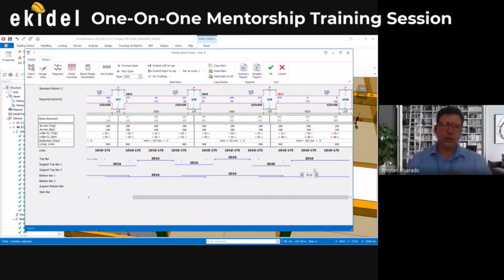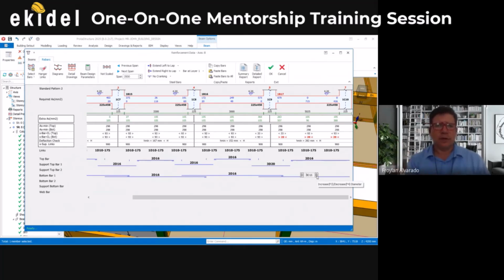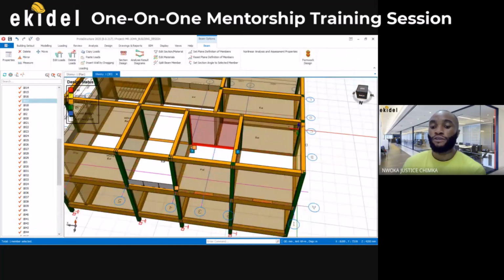But you would want all of them to be the same, no? Exactly. You have your cage reinforcement, and then you have your additional reinforcement, no? Exactly. So just to avoid any issue at site, understand? Just to have the same reinforcement size. So you can choose to check all of them, just to be sure that you don't have different diameter of bar on just one beam. You understand? So you can control that by checking all of them and say, okay, that's fine. So that's how to do that.